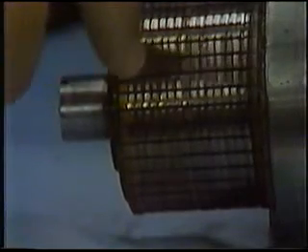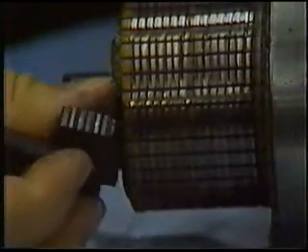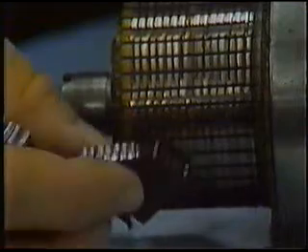DC generators are used to produce electrical power. Their operation must be regulated to ensure that they produce the correct voltage and that the maximum and minimum output is within the limits of the generator and equipment it powers. DC generators, if unregulated, could produce more power than they are mechanically capable of withstanding. Damage to the generator and/or aircraft systems could result.